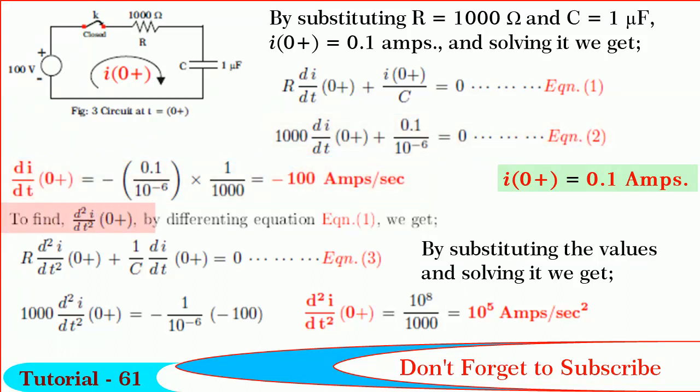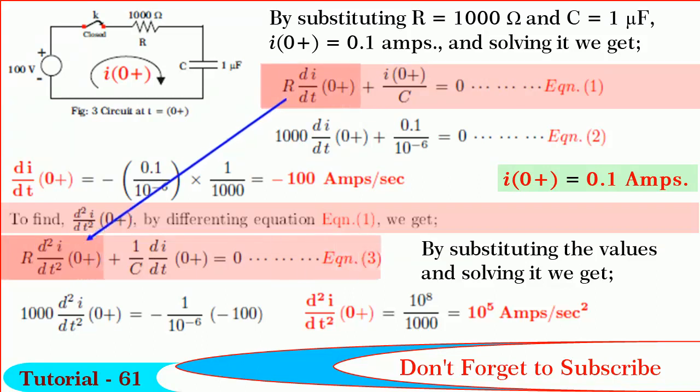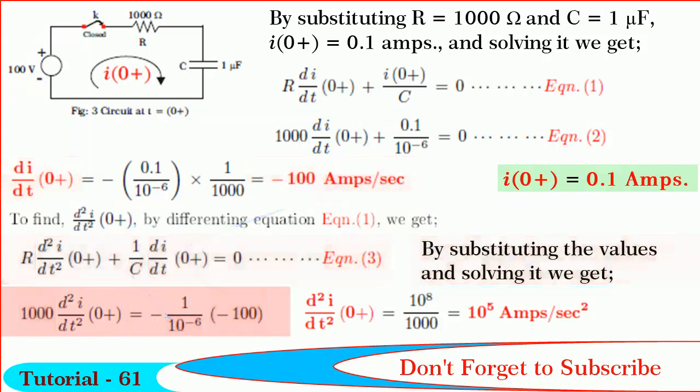To find d squared I by dt square 0 plus, by differentiating equation 1, we get R into d squared I by dt square 0 plus 1 upon C into di by dt 0 plus is equal to 0. By substituting the values and solving it, we get d squared I by dt square 0 plus is equal to 10 to the power of 5 amperes per second square. Hope it is clear to you.